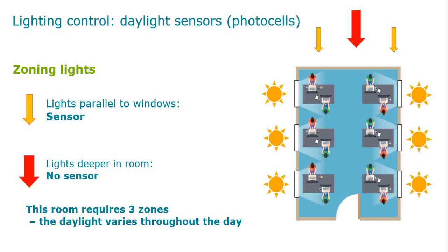Whether you could do that is sometimes down to how easy it is to change the wiring and the way that the wiring is laid out. So in this example, if the wiring was laid out across the way, that would take more work. If you had lighting with wiring already up and down, it might be quite simple for an electrician to fit photocells into an existing scheme.